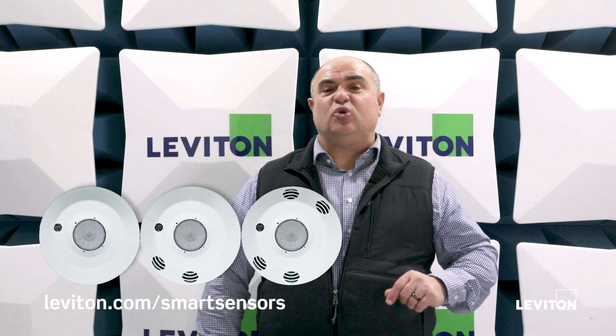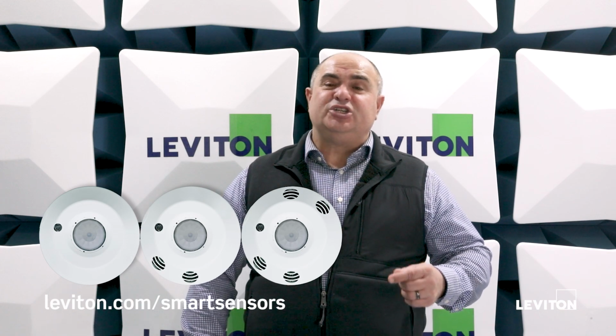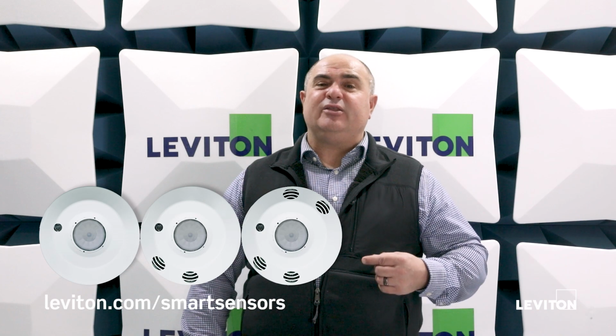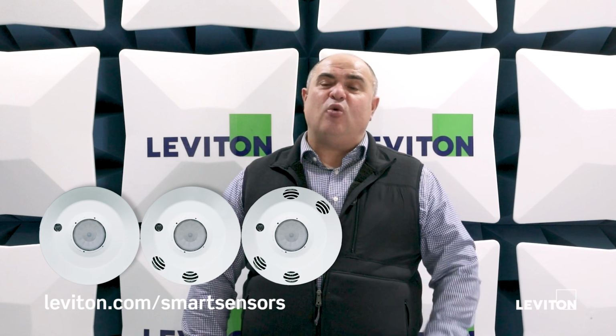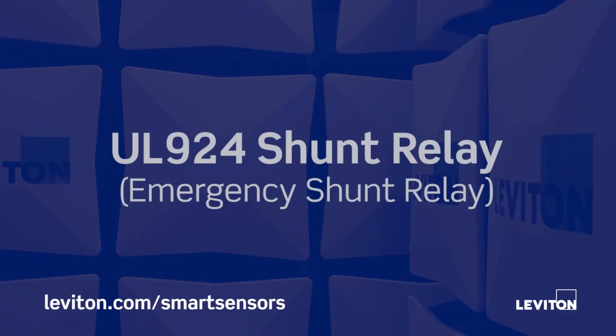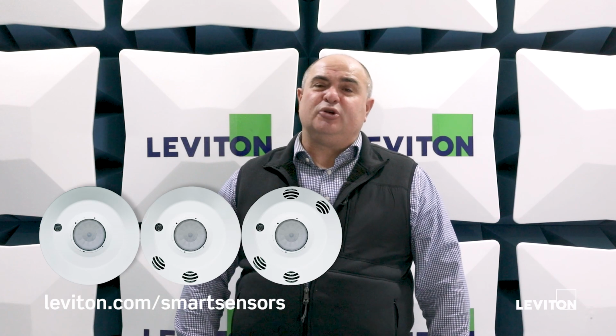We now have to control the emergency lighting just as we're controlling other lights in the room, which includes turning them off. As such, because we are now turning the emergency lighting off or allowing them to be dimmed down to lower levels, we do have to include what's called a UL924 shunt relay or emergency shunt relay in the actual applications that have those emergency lights.